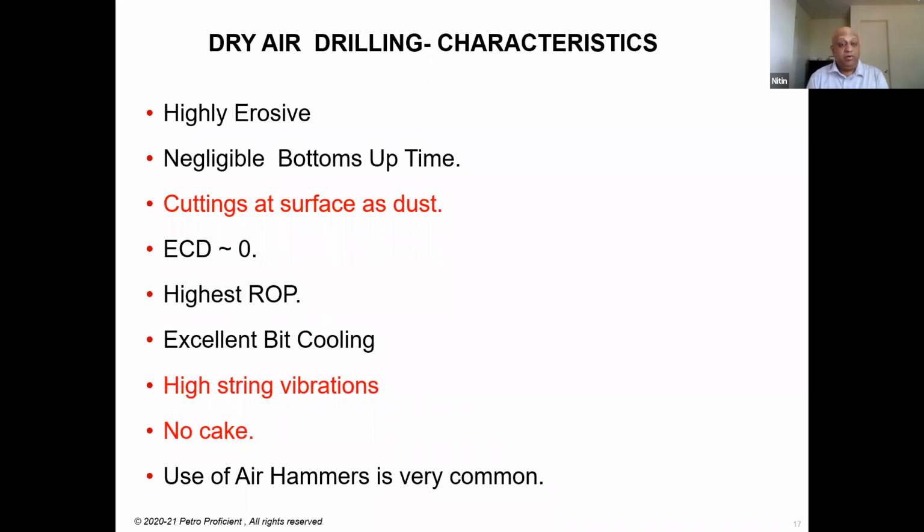There are no ECDs, and cuttings at surface are in the form of dust. So you don't have rock cutting samples at surface. It's just dust. And your ROPs are excessively high. Your bit cooling is enhanced. You can experience vibration in your string. There is no filter cake or mud cake because there is no mud system used. We are just using air to drill.